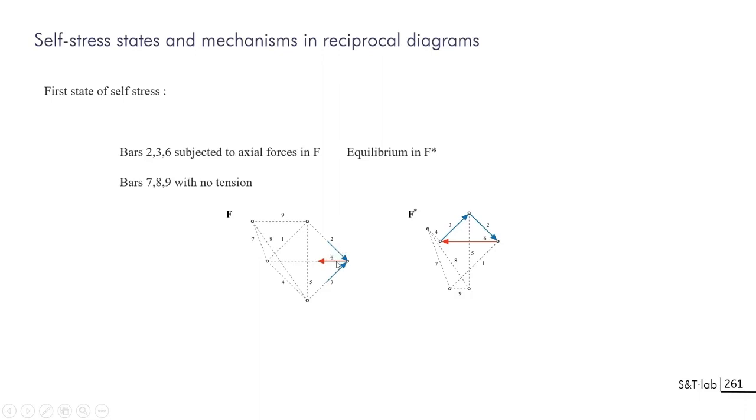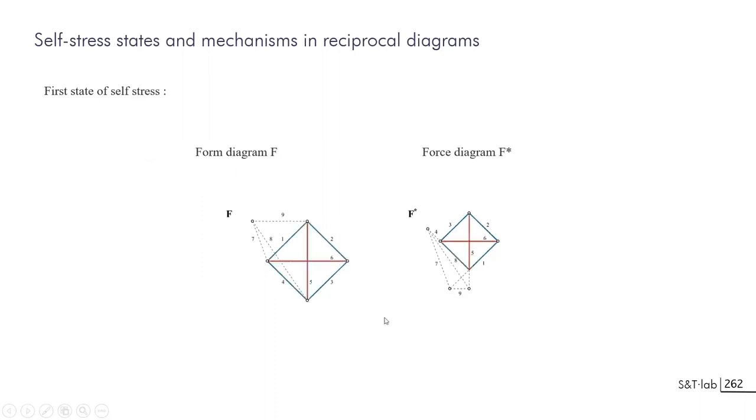If you are looking to the force polygon, you can see that indeed this self-stress as a tension on a bar here will be equated with 2 vectors coming from each of these forces. If you solve this, you know that having compression here and tension here, you will need compression on the other bars, and tension to equilibrate the system. And we'll have on the complete force diagram what will be the component that will be linked to these forces.